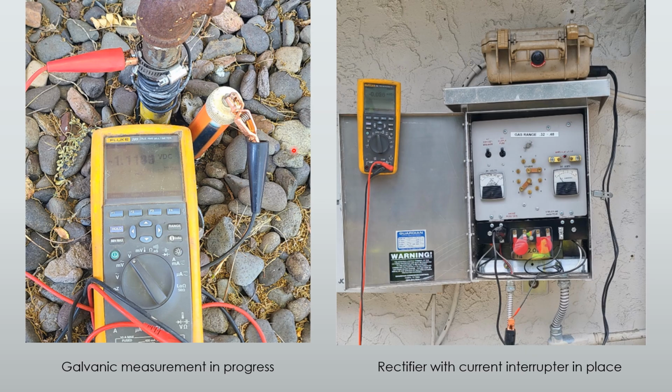Just kind of a practical thing. This is an on reading of a gas pipe. This is a propane line. I've got the reference cell jammed right up against that pipe as tight as I can get it to try and reduce that error. So I am taking an on reading, and I've got 1100 millivolts. That's pretty good. If I was at negative 850 and I was only at my on, then you have to start wondering if this system needs new anodes.